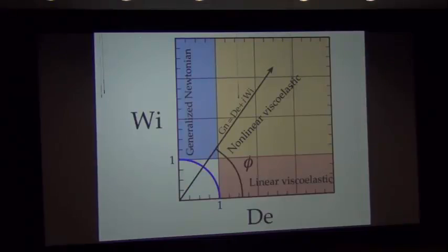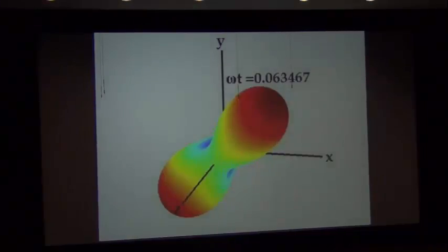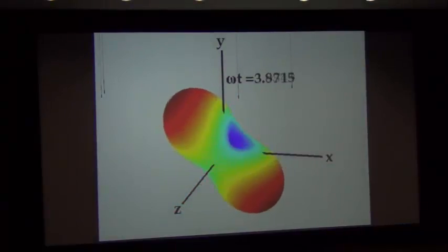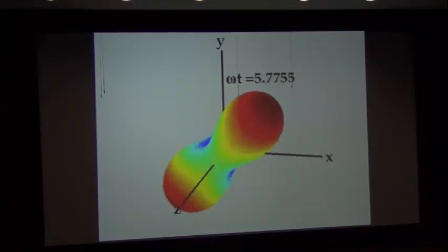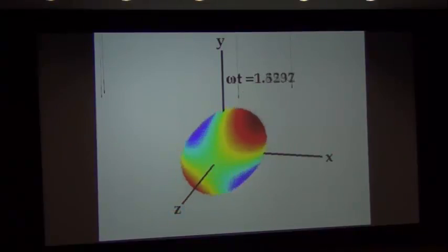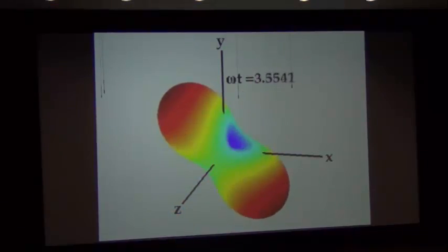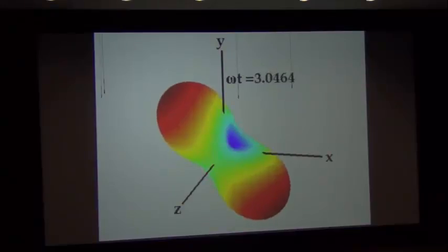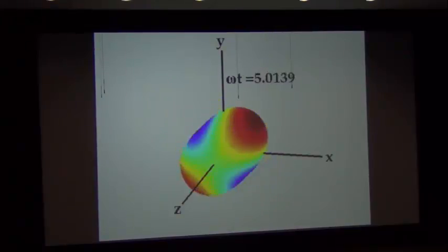Okay, one more movie for you here, but remember I told you the most exciting area would be out here in the large amplitude oscillatory shear deformation, so let's have a look at this. And now I like this peanut shape because after years of research on this subject, this is at least my first glimpse at what is causing the higher harmonics. Remember, this is the orientation distribution function that we use to calculate that third harmonic in the molecular theory, for instance.